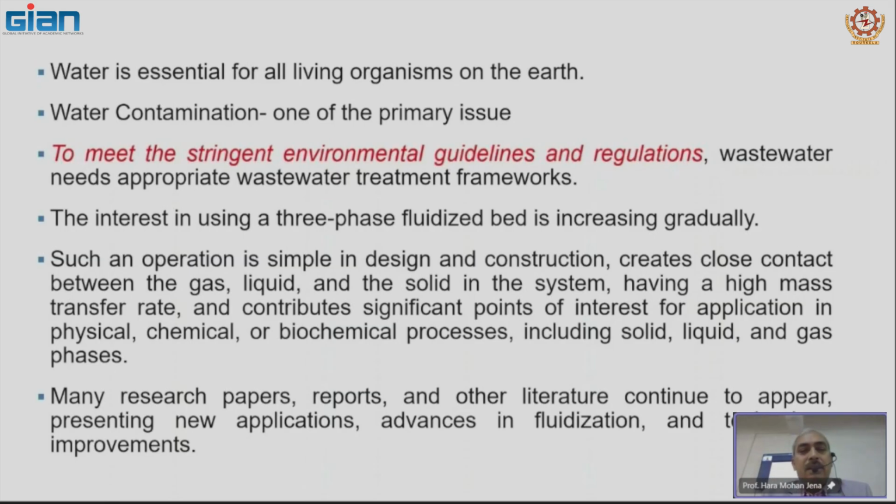Why this three-phase fluidized bed? Because this operation is simple in its design and construction, and this three-phase fluidized bed creates close contact between the gas, liquid and the solid in the system, having a high mass transfer rate, and contributes significant points of interest for application in physical, chemical and biochemical processes, including solid, liquid and gas phases.